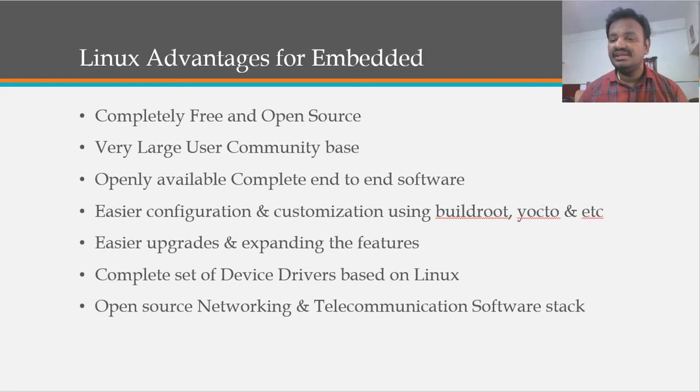And we can easily configure and customize using tools like Buildroot, Yocto, and OpenEmbedded. We will see those one by one, but they have the complete features to create your own embedded Linux image, and make it easier to upgrade and expand features. And we have a complete set of device drivers based on Linux, which can easily be moved forward to the embedded platform we are developing. That's called driver porting; we will see what driver porting is in our next sessions.